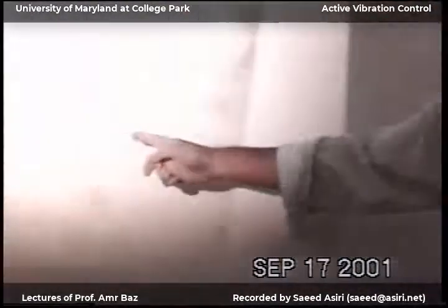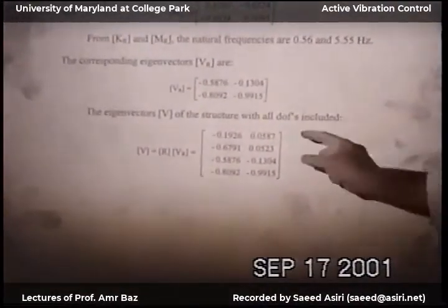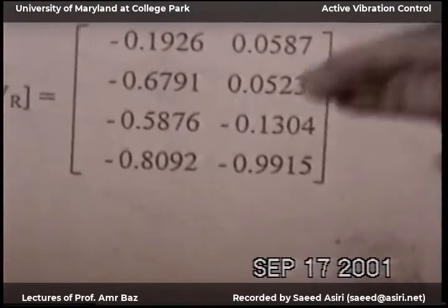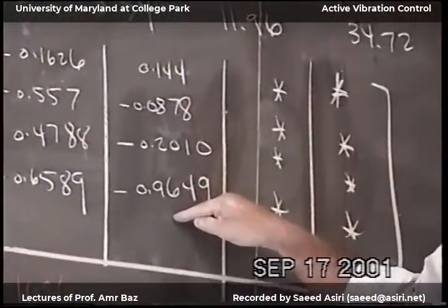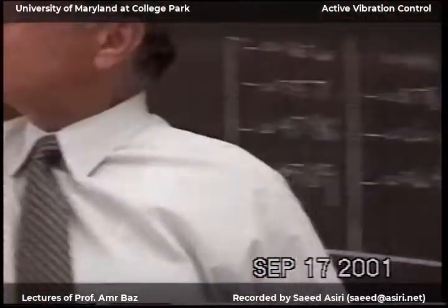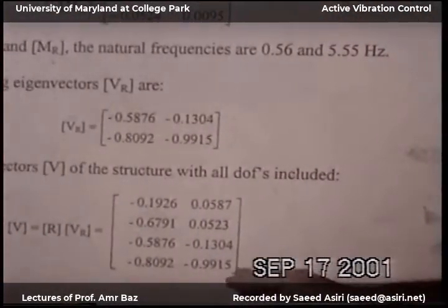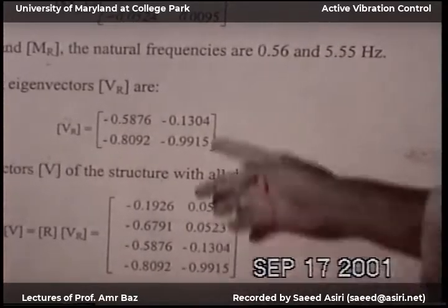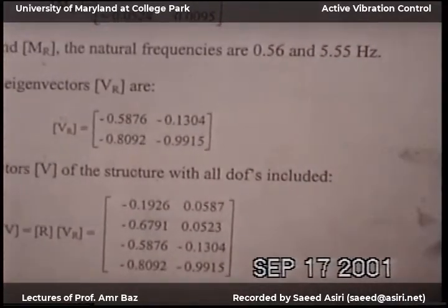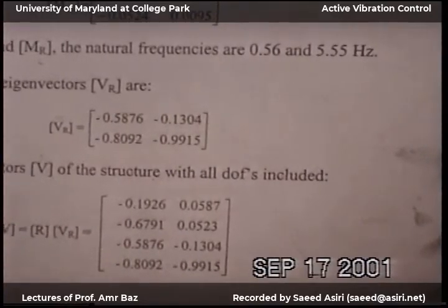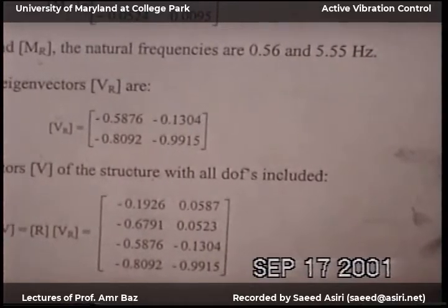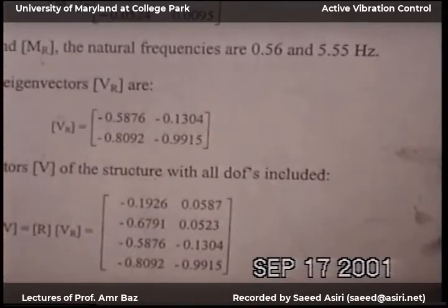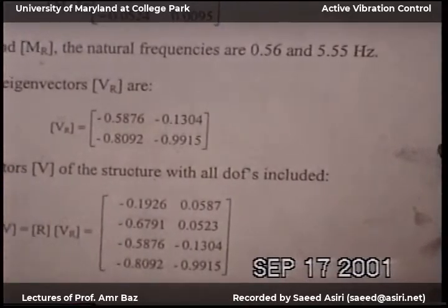Look here. I have half positive and then the other half is negative. Not like here. Here I have only 1/4 positive and then the rest is negative. Why? This is wrong already or very far. So I don't expect a miracle. This is also very far. But the first eigenvector and the eigenvalues are very close. So if you want good results or a simple model, make your order reduction intelligently, so you can make your model very compatible to your practical application.